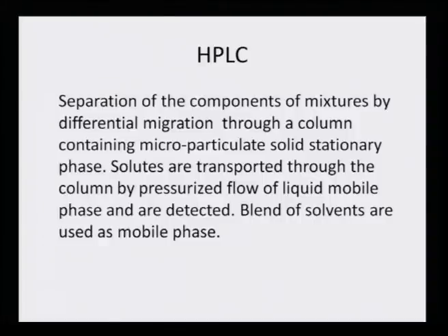A blend of solvents is used as a mobile phase. So, here the non-volatile compounds are identified, because they have different rates of movement with the mobile phase on the stationary phase, which causes the separation, and by pressurized flow of the liquid they are made to flow towards the detector end.